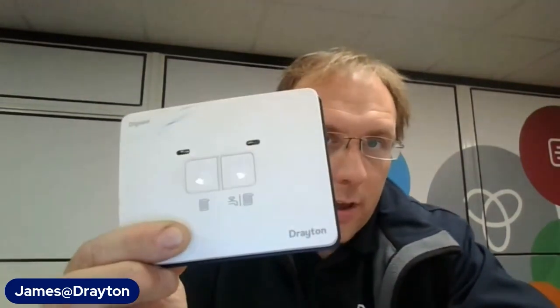So if you want to give the customer some instant capability to improve their efficiency and essentially give them load compensation, you can take the programmer off the wall, so take the HE off the wall and install this on the backplate. The only bit of wiring you're going to need to do is, if they had a wired room stat, which you would hope so, you'll just need to link that out in the wiring center. But this is a really good way of being able to give them some sort of smart control.